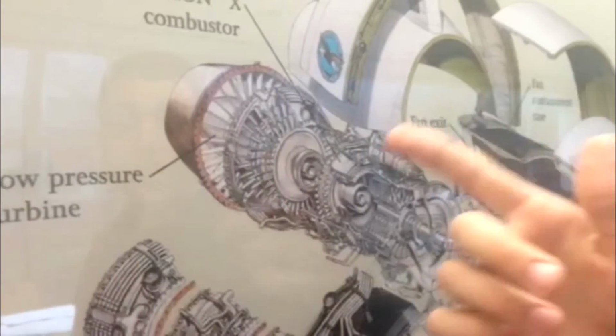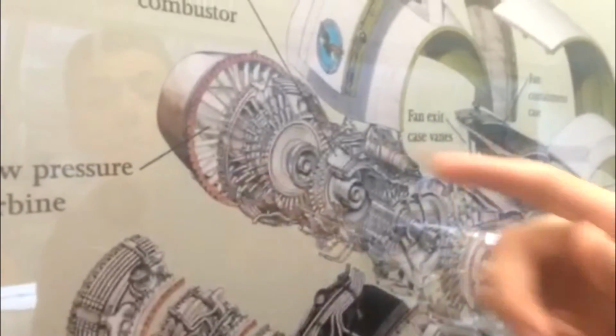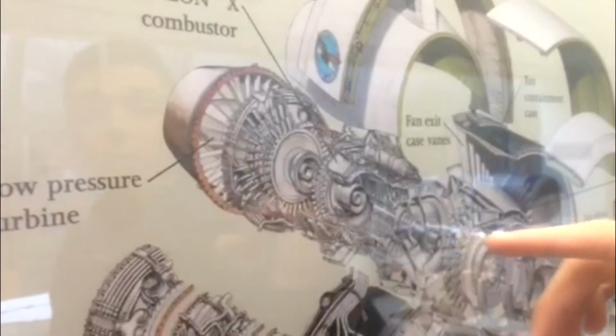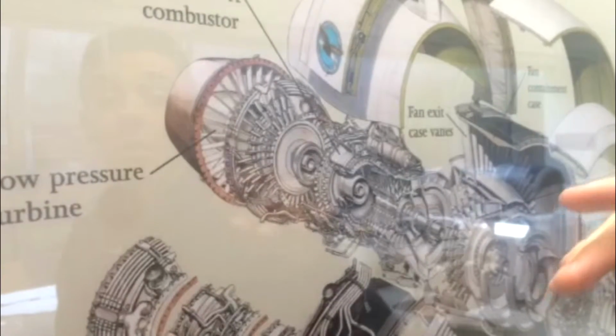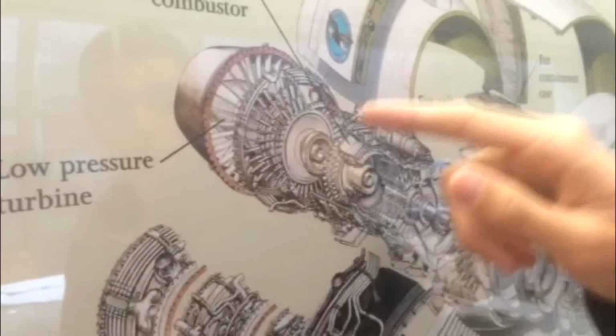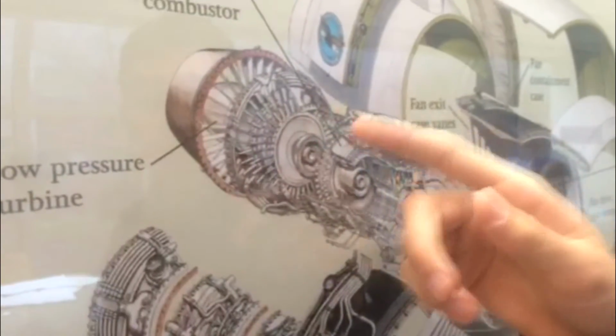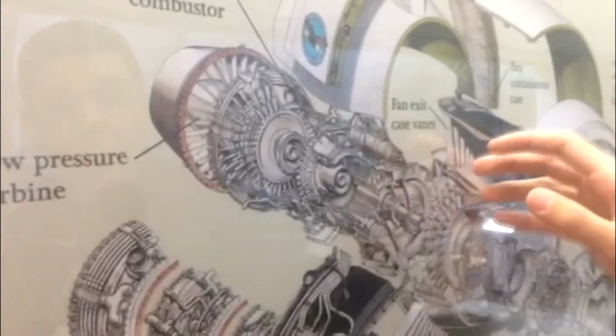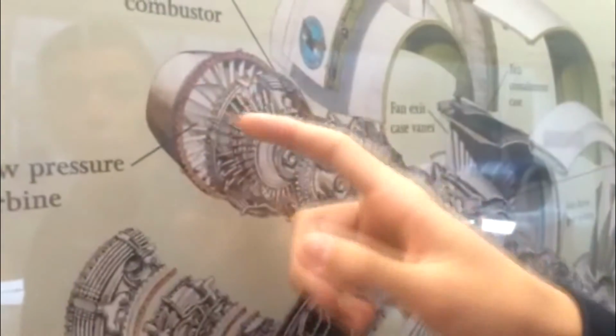In the turbine, airfoils can reach temperatures of up to 3,000 degrees Fahrenheit, which exceeds the melting point of the materials. To solve for this problem, this area must be air-cooled. However, the less amount of air, the better. To solve for this problem, thermal barrier coatings have been invented that are sprayed onto the materials to act as an insulator, allowing less amount of air to be required to cool off the materials.